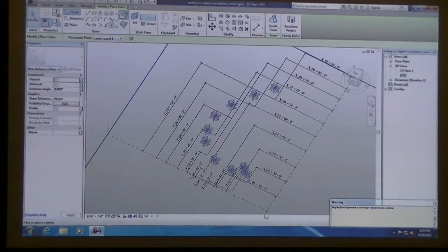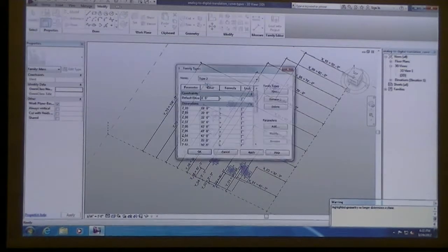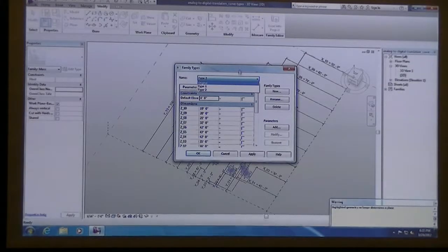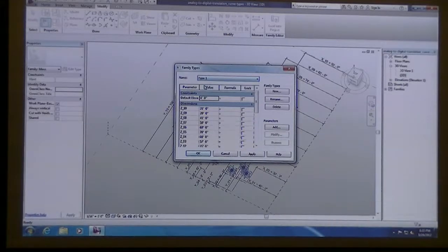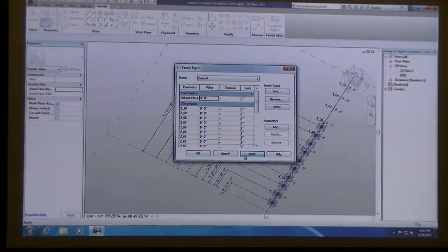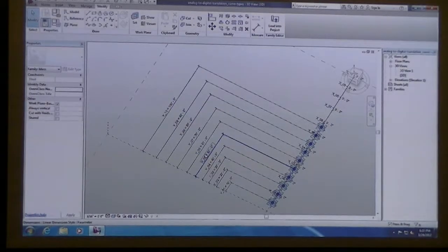Okay. You might want to save what I did at the very beginning. If you remember, you created a set of points that were basically in a straight line, and then you did your spline through points. And I actually saved in my types the original setup. You may want to go back to something similar so that you can come in and add the amount of points that you need and make sure you get that spline to go from point 1 through 10 in order, or however many points you're going to need. Okay. Where was that dissolve button?